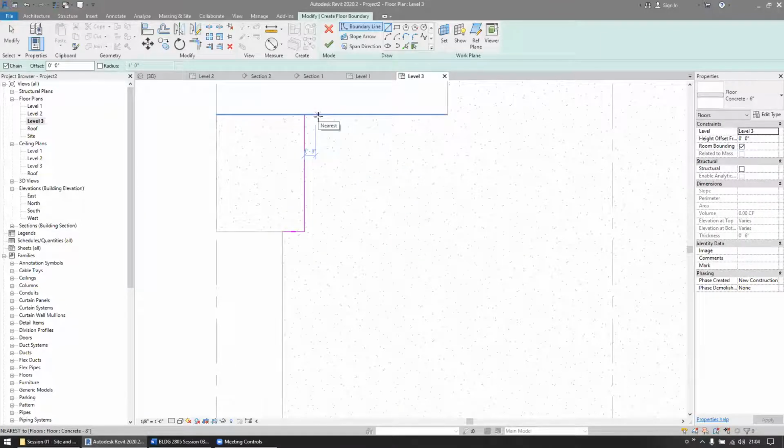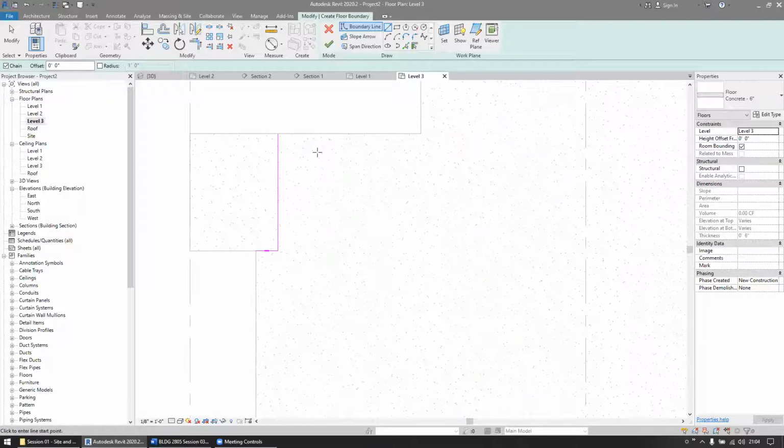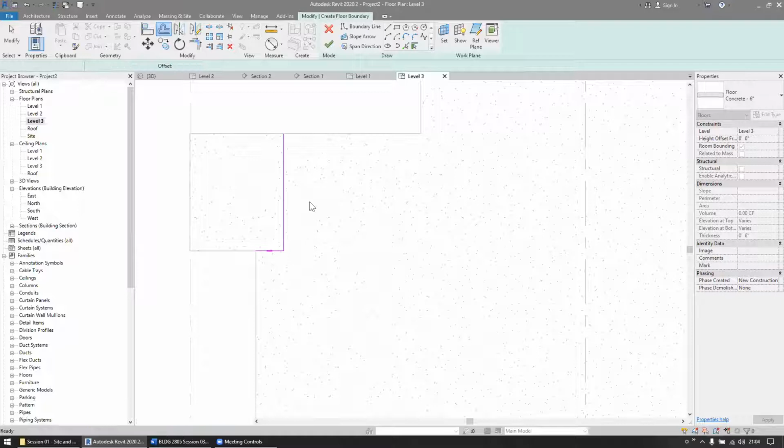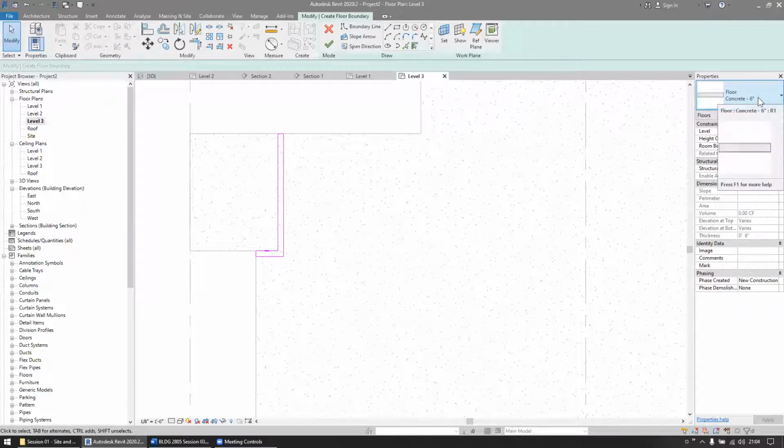and then the next thing, of course, is you have to decide what the width of the curb is. So if it's a 6x6 curb, I'll just offset it 6 inches here. So there's my curb, and then I will just cap off the lines at the end. So the trick here is getting a floor object that provides the thickness required for the curb. And then the next trick is to elevate that curb by that same amount.